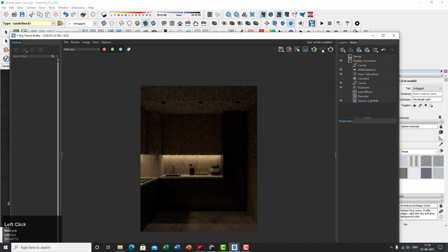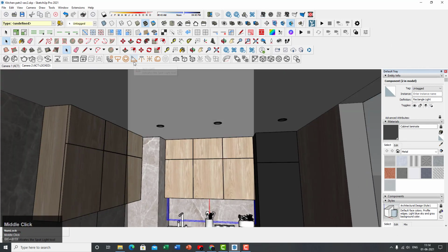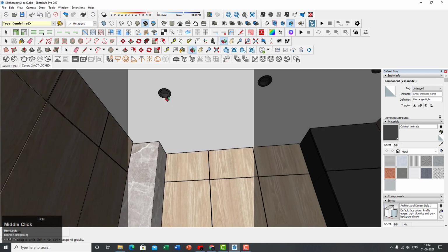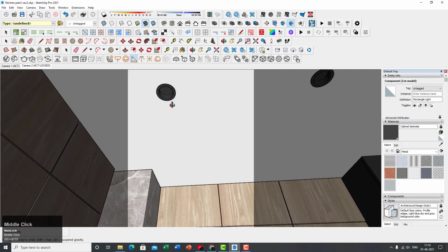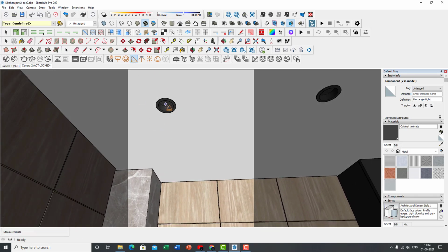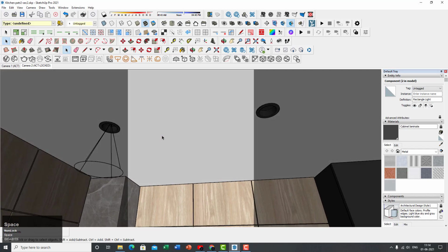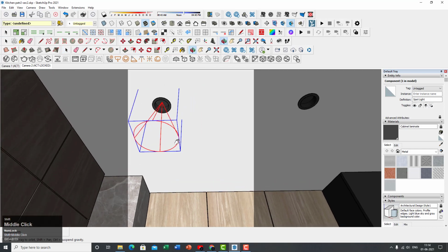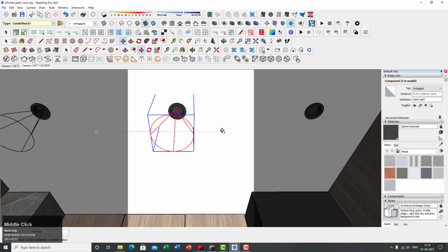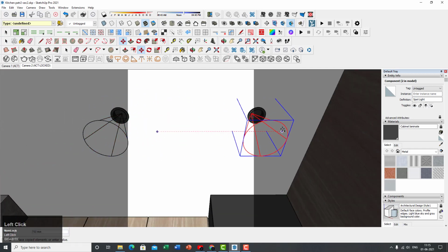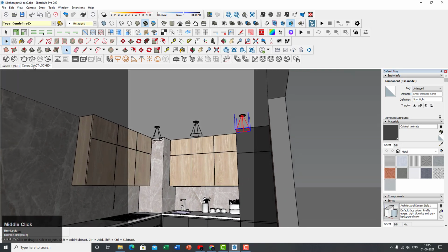So switch off the interactive render for now and cross that. The other light that I'm going to put in over here is spotlights. So click on that spotlight, and again you're getting an option over here whilst you're switching on the spotlight button. So you can just snap that there in the middle of that, just click there, and you should have that spotlight there. So I'm just going to hold that spotlight, M, control, copy that there, and then again control, copy that there.